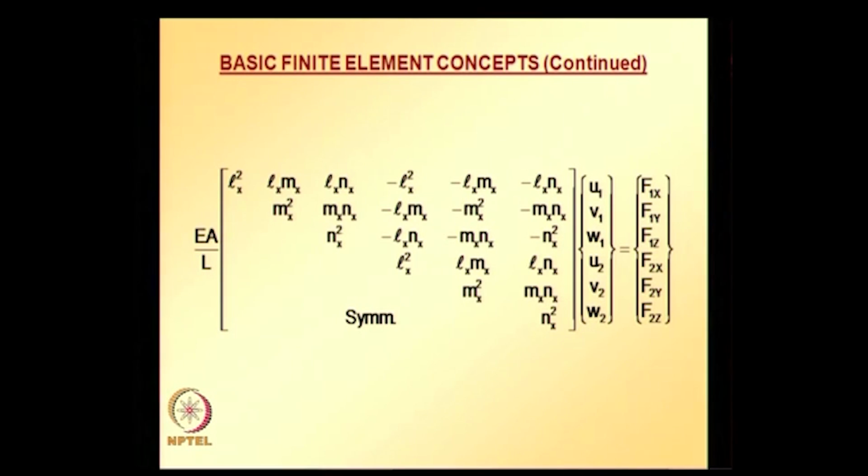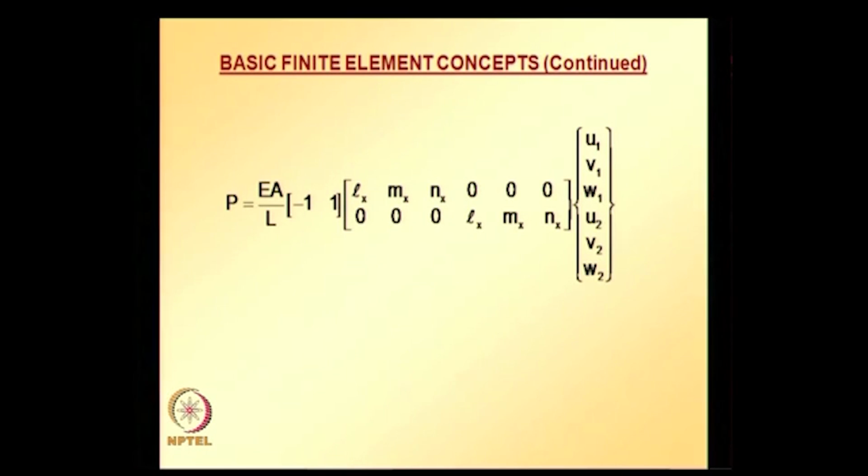Axial forces can be computed by transforming displacements back to the local element coordinate system. So, once we get the global displacements, we can calculate local displacements. Once we get local displacements, we can calculate strains and then stresses, and using those values we can calculate the forces in a 3D truss element. The equation is given here, and this equation in terms of direction cosines after manipulating the first equation is shown there.